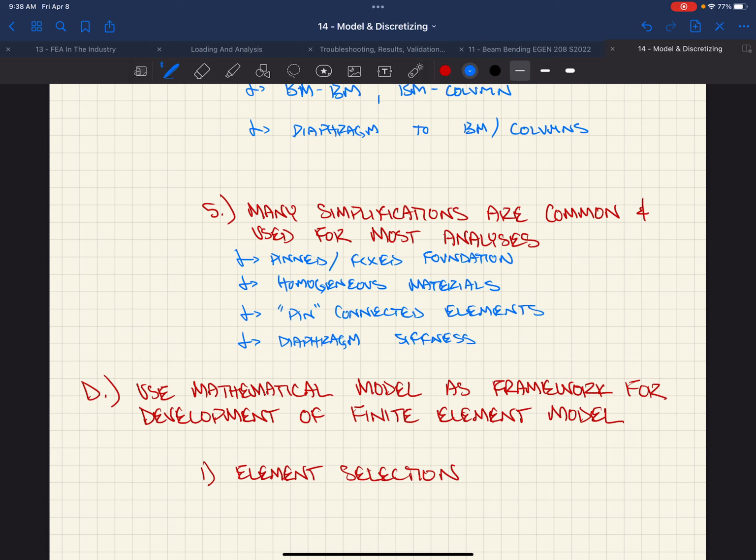So you're saying this beam does this, and it does this. 2 simply supported beams sitting right next to each other gives you this, right? Is this diaphragm that could be like 30 feet deep, does it behave like there's a hinge? Do you think there's gonna be a big hinge here? Depends on where their sheathing gap is.